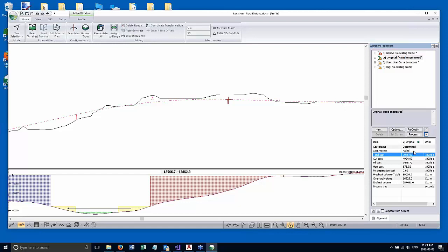An interesting thing about Optimal is that for projects like highways and railways, where you've got some fairly severe limitations in terms of needing very smooth curves and gentle grades, the optimizer works very well. I would say it works better than for lower standard roads like resource roads, where the tendency is simply to follow the ground. You can't do that in a highway. You need nice gentle curves, and you can't follow every dip and bump in the ground. So the optimizer is really good for this.